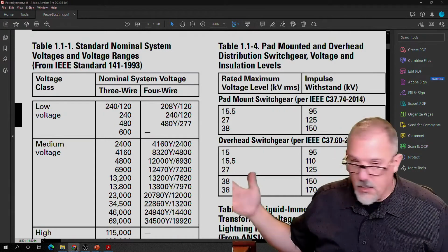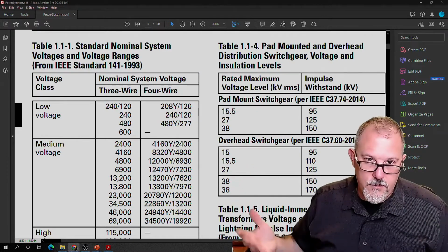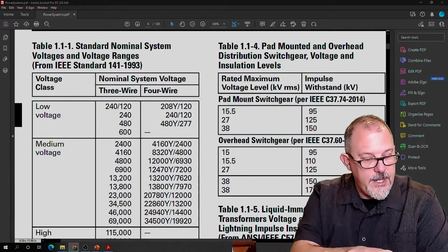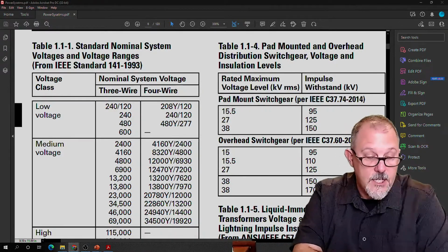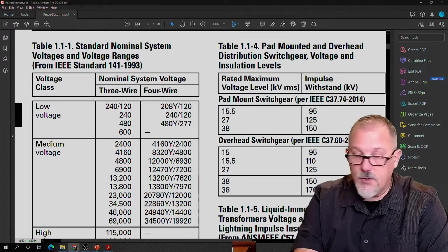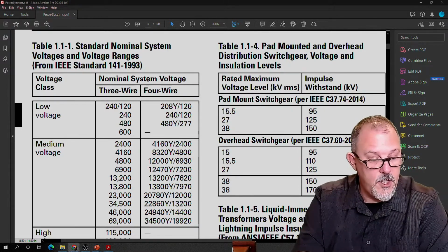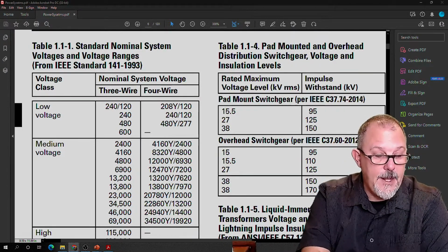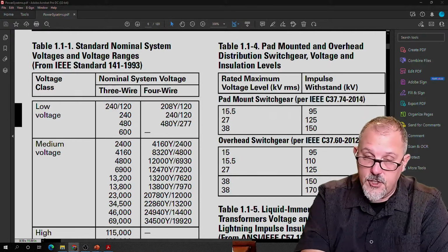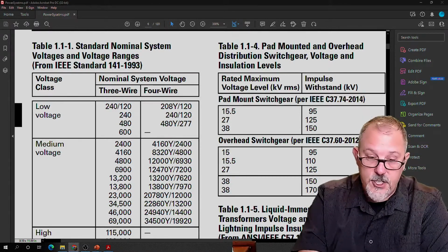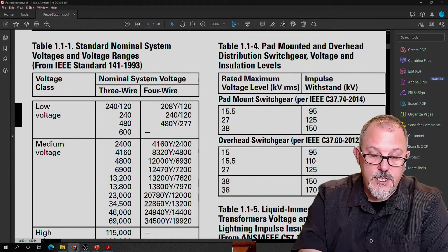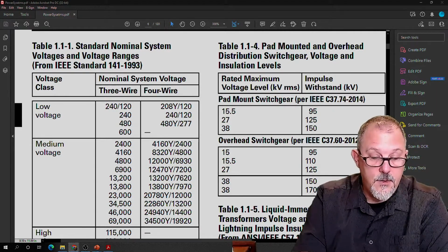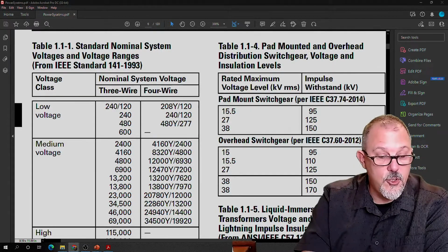It doesn't necessarily have to be a large rotating piece of equipment that you have for, I don't know, a manufacturing process. So a voltage variation, say on an induction motor: if you're at 90% of voltage, so it's a 10% reduction, the starting and maximum running torque will vary as a function of voltage squared. So for a 90% voltage, that's 10% low, you'll decrease the starting and maximum torque by 20%, or 19%.